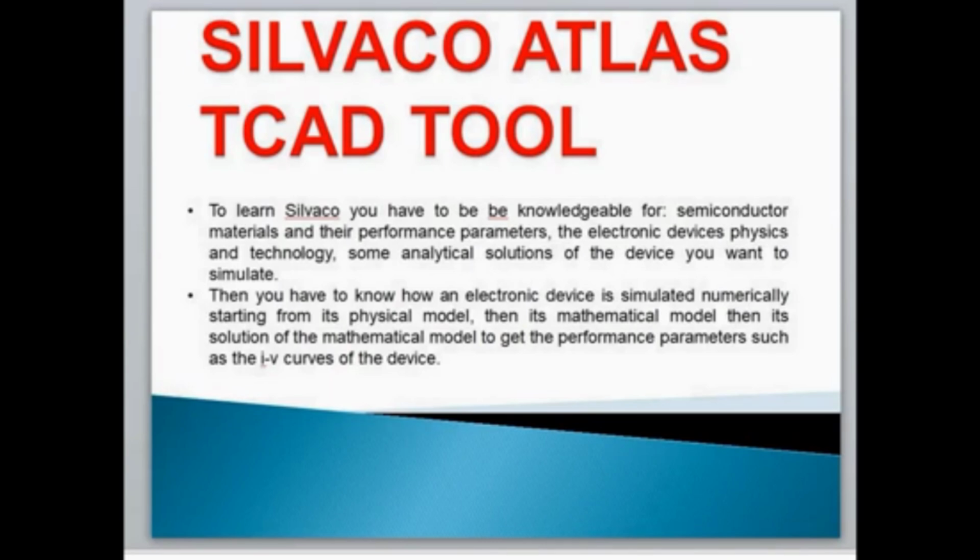Silvaco Atlas TCAD tool. To learn Silvaco, you have to be knowledgeable about semiconductor materials and their performance parameters, electron device physics and technology, and some analytical solutions of the device you want to simulate. Then you have to know how an electron device is simulated numerically, starting from its physical model, then its mathematical model, then the solution of the mathematical model to get performance parameters such as the IV curve of the device, and finally the post-processing of the computational results.